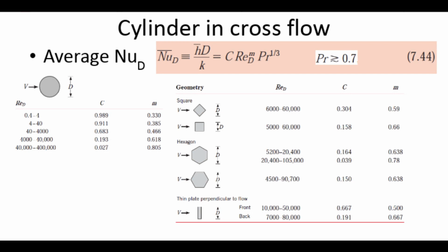And look at this. If you have really laminar flows, Reynolds is to the 1/3 here. If you have turbulent flows, you see how big this is. They don't talk about a transition to turbulence anymore. They don't tell you, but you know it is there. This M that is changing, you see 4/5 here? This is 0.8. And look, for the very high Reynolds numbers when it's very turbulent, this is 0.8. You see the plate and the cylinder share so many similarities.